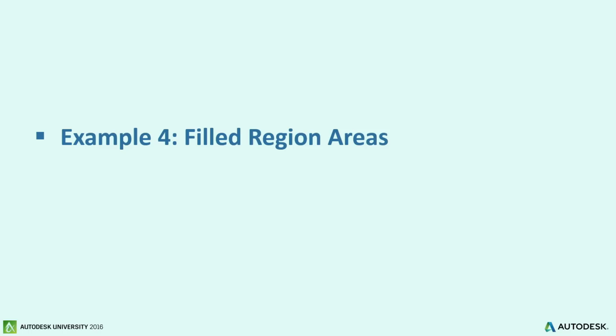Actually, on that last slide, there's one thing that we stumbled on yesterday in my advanced workshop. If you have a thing selected inside Revit, like let's say you click on the title block and you leave it like that and you run the script, it won't run unless you hit escape. So you've got to make sure that nothing's selected inside Revit for the Dynamo script to execute. You may think that there's something wrong with the Dynamo side. It's the fact that Revit's not allowing it to execute until you escape the command, just so you know. I've seen that.